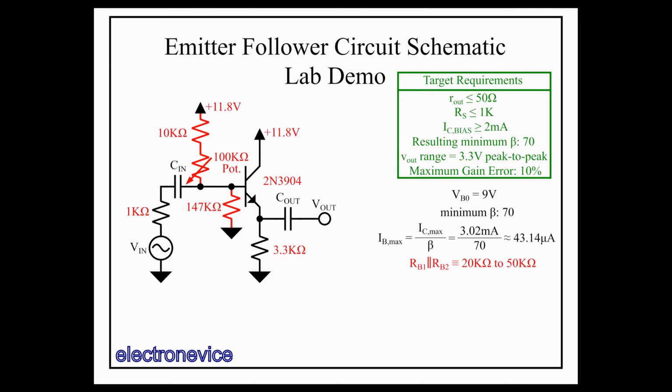With 50K of biasing resistance, the total contribution to the base voltage due to the base current is equal to about 2.157 volts, which translates to a collector current deviation of roughly 654 microamps. Most of this deviation will be removed when I compensate for it with the initial setting of the base voltage, and the remaining deviation due to changes in input voltage will be significantly less than this, as beta will not vary all that much over the application output voltage span. So we should be fine.